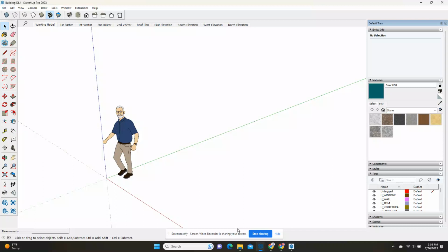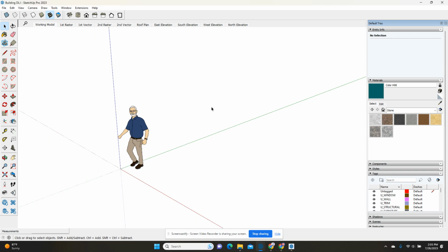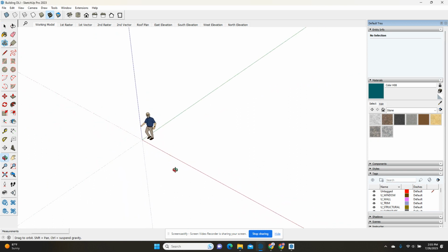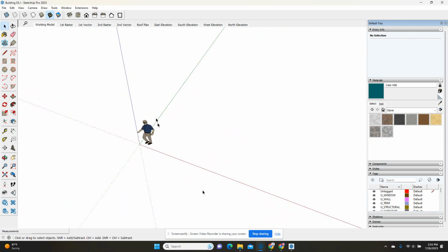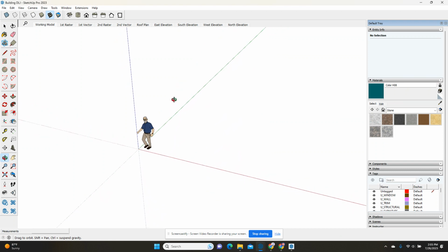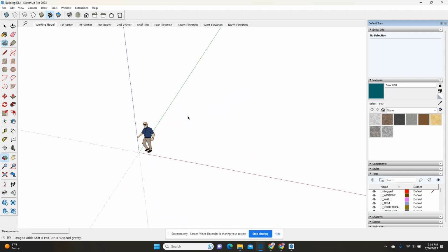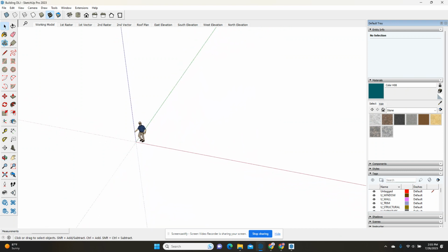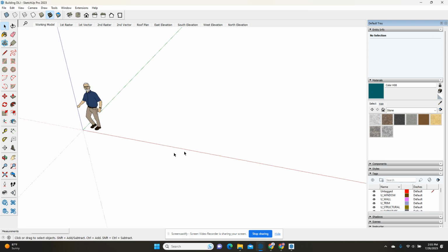So the first thing you want to do is just get into your building drawing, and you should have your large tool set right here. And we're just going to start drawing this picnic table by drawing a couple components on the table. So I'm going to kind of get to a top view, and basically all I'm doing is moving my mouse to a location, pushing down on my wheel button. That allows me to orbit my drawing. I want to kind of get in a top view here. So I'm going to draw the first component here.